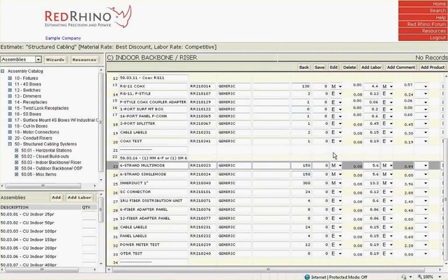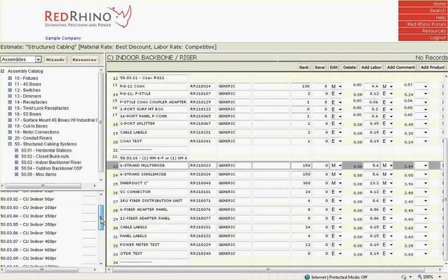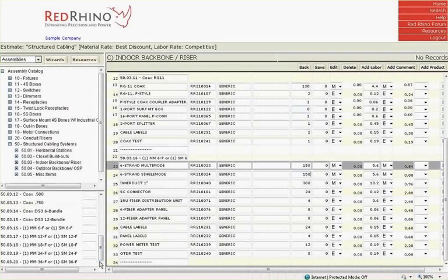Now if this was a composite cable, let's say it's a 12-2 composite, I'd go over to the left and select that fiber. Go down here on the bottom, scroll down to the bottom here, and see what your different fibers are in there. I would select a 12, whatever you want, type in the quantity and click add there. That's how you do it.